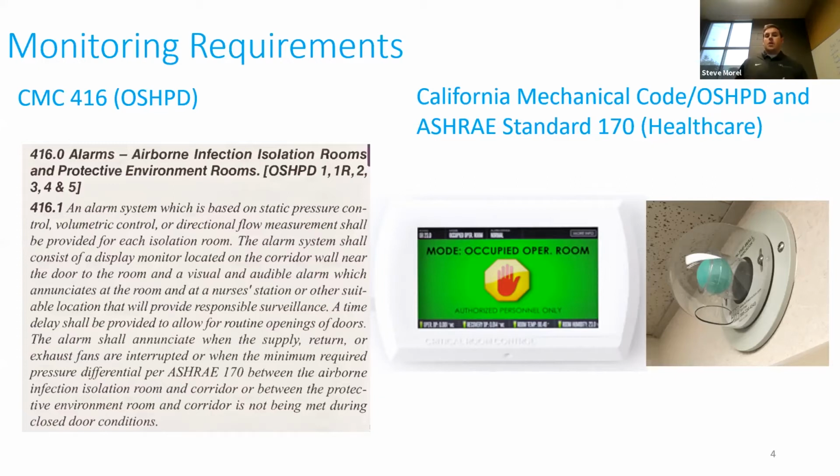and that ball on the wall only helps that nursing staff when they're looking at it. It doesn't have any audible alarm. It doesn't give you any other indications if the room is occupied or unoccupied, if it's achieving the right air change rate. And again, it only really emphasizes the pressurization when you look at it. If I'm not looking at it, the room could go unoccupied or could lose pressurization, and I would have no idea that this room is unsafe.